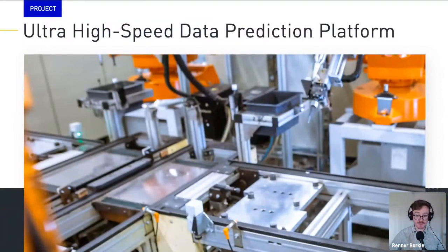Now, the gotcha for this project is that their entire process of bending metal only takes 1.2 seconds. So that means we only have those 1.2 seconds to build our entire prediction model. And I'm sure you could figure out, if we're only capturing a couple of sensor readings per second, we're just going to end up analyzing pure noise and be lucky just to have a handful of readings to try to build that model. And really, we wouldn't find anything meaningful out of it.